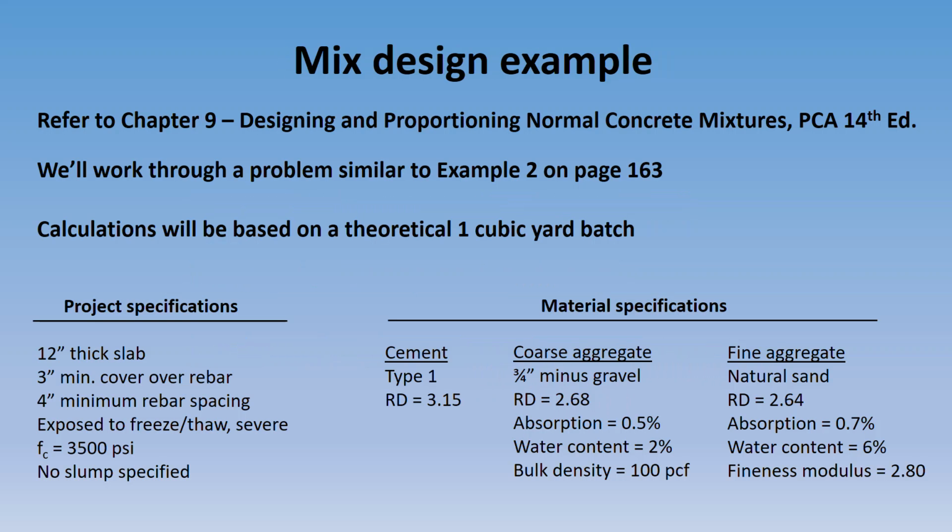For our purposes in labs, when we're working on testing it, we batch down. So we go down to 1 cubic foot, or more commonly, even a half of a cubic foot. So when we get these final numbers at the end of our mixed design, we'll talk about batching up or batching down based on the specific use.